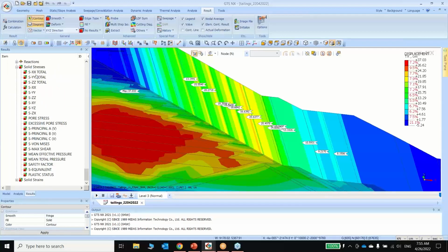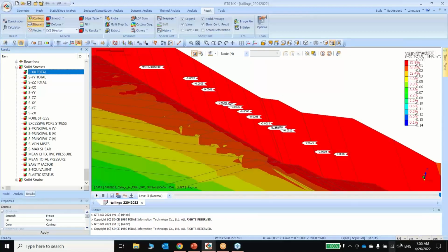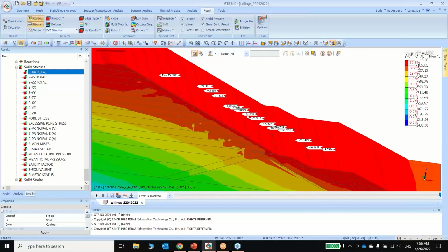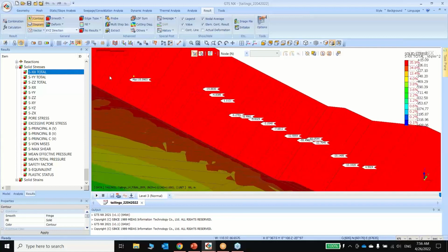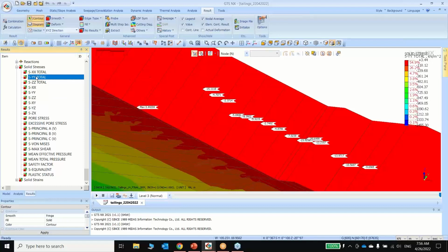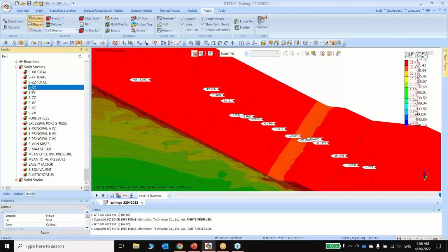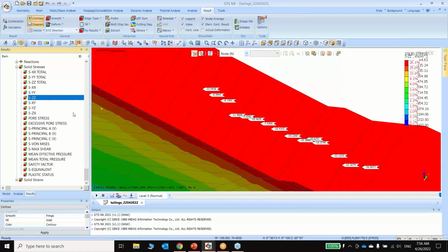So now finally coming to the stresses. I just change the unit to kPa. Total stress on the edges. You can see on these edges we don't want very high tensile stresses, because that means it will collapse. Compressive stresses are negative, tensile are positive. So look for the effective stresses. They are in the negative zone. This positive 15 kPa might become a concern area, in the vertical stresses.